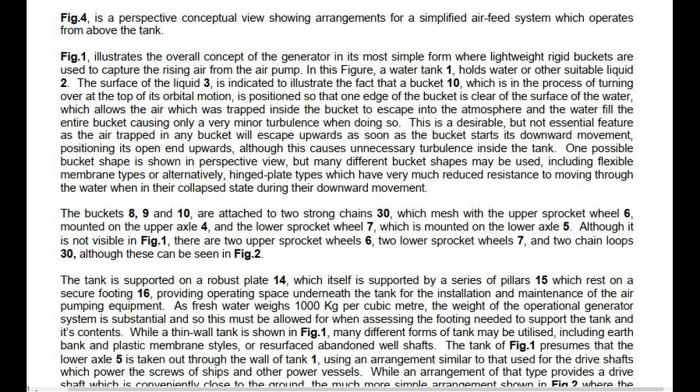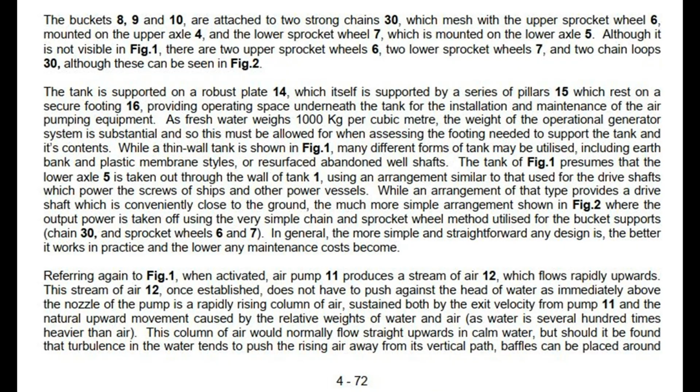While an arrangement of that type provides a drive shaft which is conveniently close to the ground, the much more simple arrangement shown in Fig 2, where the output power is taken off using the very simple chain and sprocket wheel method utilized for the bucket supports, chain 30 and sprocket wheels 6 and 7. In general, the more simple and straightforward any design is, the better it works in practice and the lower any maintenance costs become. Referring again to Fig 1, when activated, air pump 11 produces a stream of air 12, which